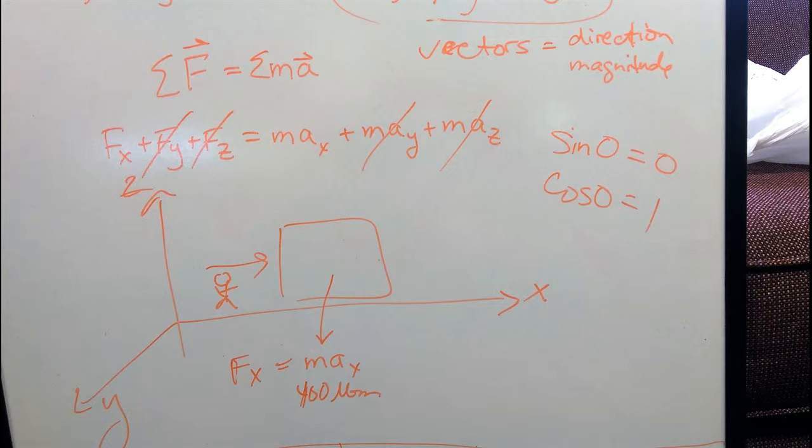Now, for the friction due to gravity, that's pretty simple. We're going to use the coefficient of friction times mass times gravity times the cosine of theta. Because if you look at this chart here, you can see pointing down is the 400 pound mass, or force rather, pound force. In a way that is perpendicular to the slope, we have our mg cosine theta, which is the actual downward force.